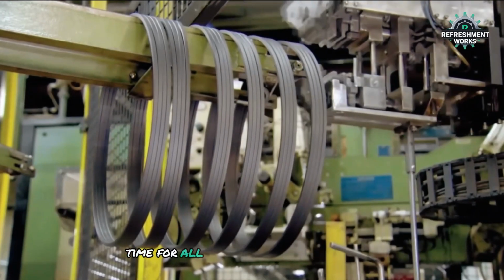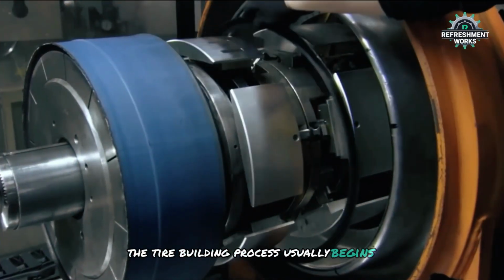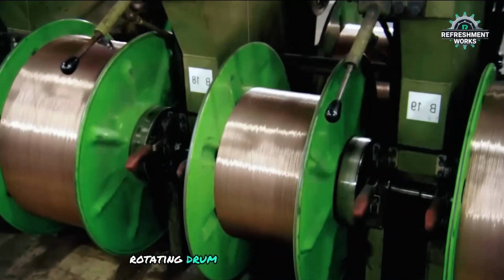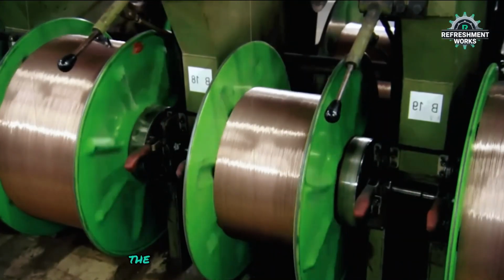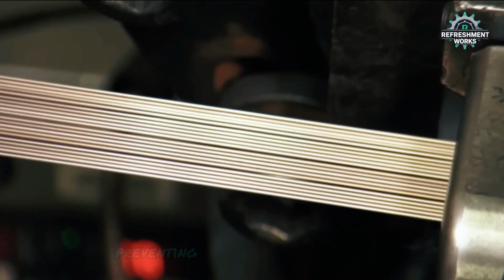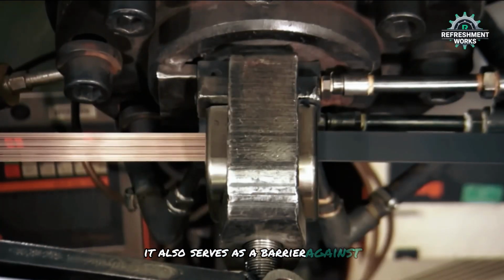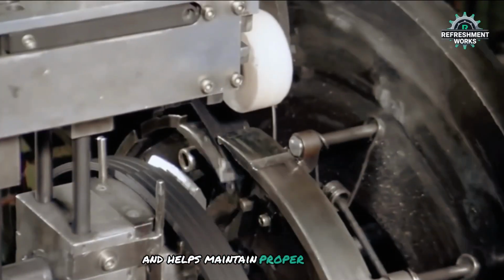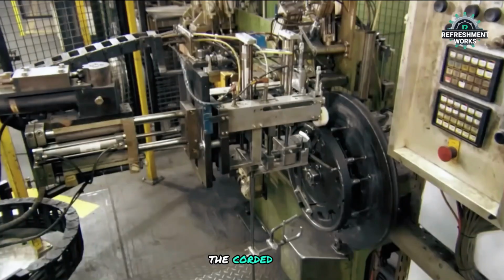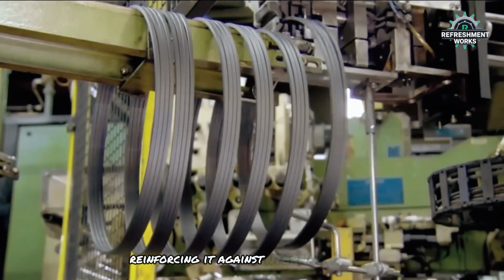Finally, it's time for all the elements of the tire to come together. The tire building process usually begins with a worker placing the bead rings on a special rotating drum. Next up is the inner liner. The inner liner is a thin layer of rubber that provides an airtight seal, preventing air from escaping through the tire. It also serves as a barrier against moisture and helps maintain proper inflation. The inner liner is then covered with the corded ply. The corded ply provides strength and stability to the tire, reinforcing it against internal pressure.